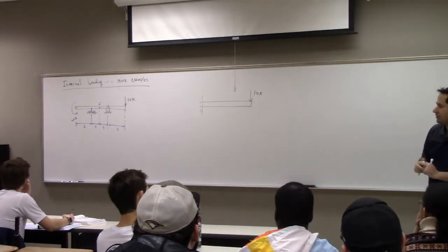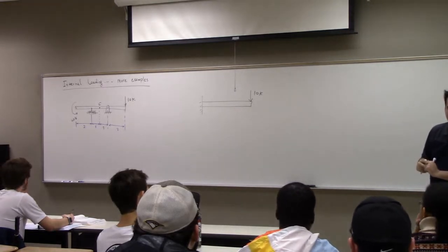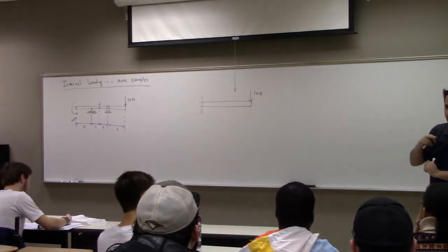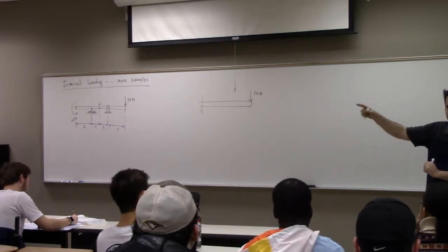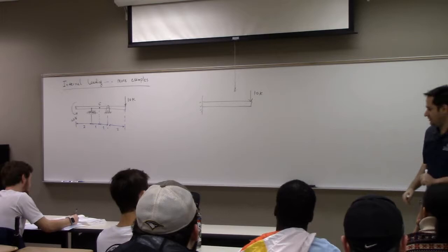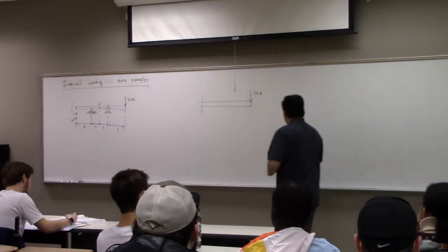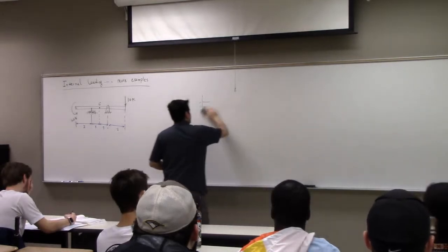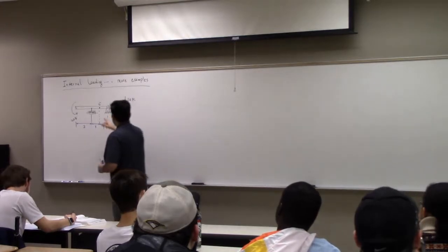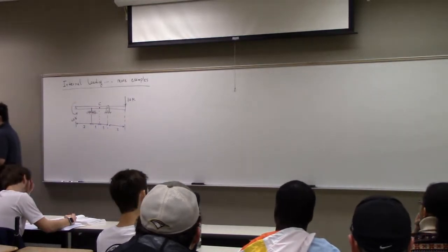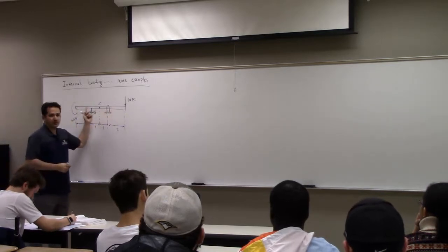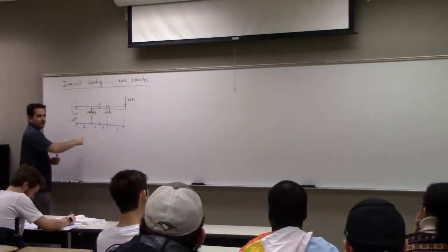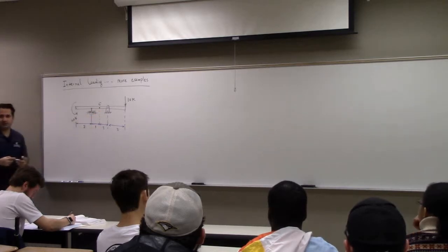And this is a good introduction to the diagrams. We do bending moment, shear force, and axial load diagrams. A diagram means just a simple plot versus various locations. So this is just an introduction to that concept. That's the reason we are interested in doing this sort of computation at more than one point. Right now we start with just one point, and then we go to another point here, another point here, and then we connect all these dots together to get the final diagram.